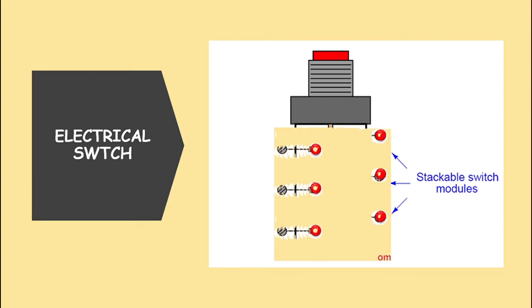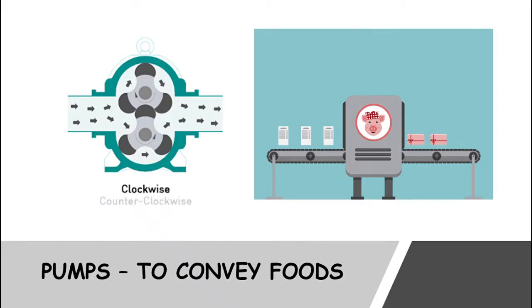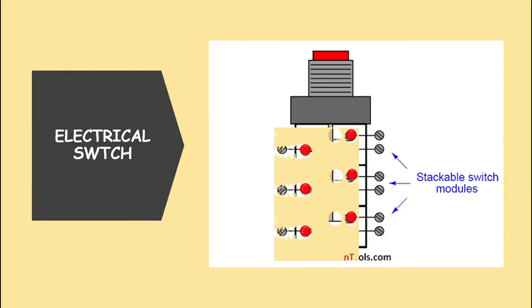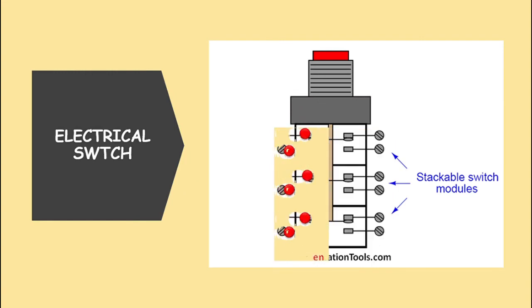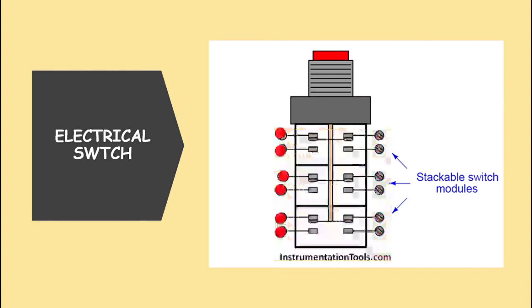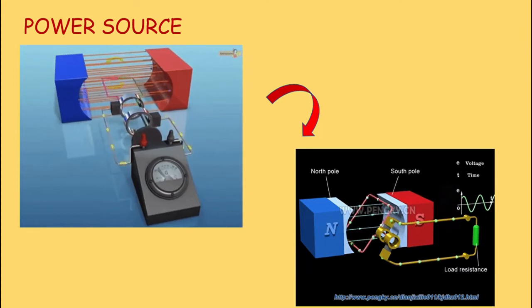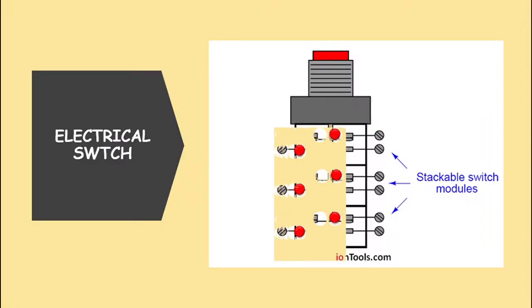that provides a relatively constant voltage across the pulse width. The power source, a high voltage DC generator, converts voltage from a utility line into high voltage AC that is rectified to a high voltage DC. Energy from the power source is stored in the capacitor and is discharged through the treatment chamber to generate an electric field in the food material. So, the maximum voltage across the capacitor is equal to the voltage across the generator.